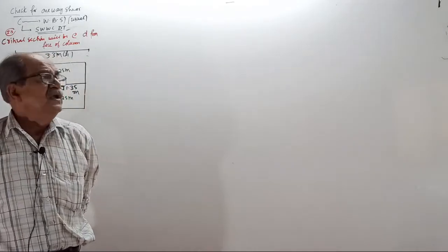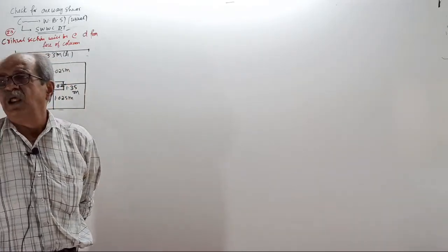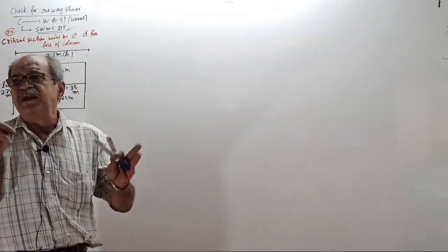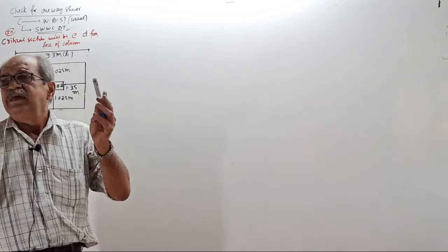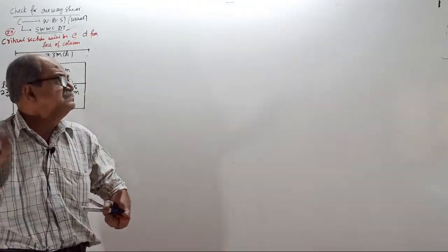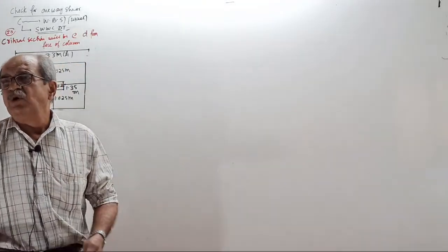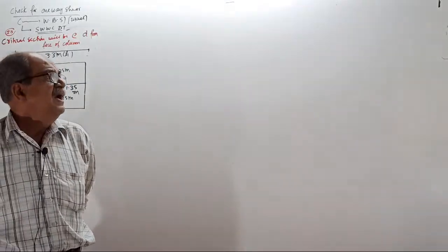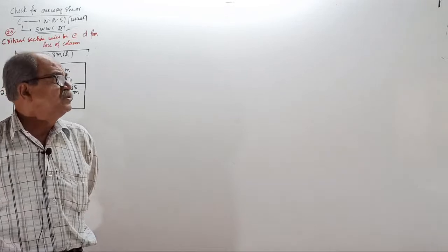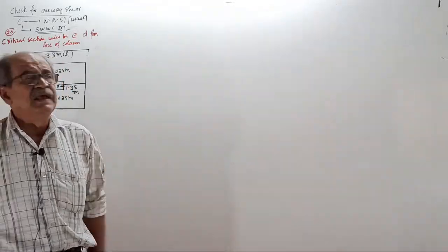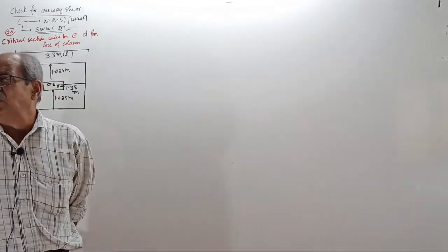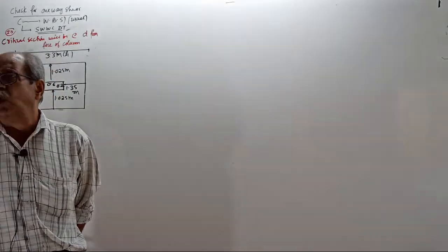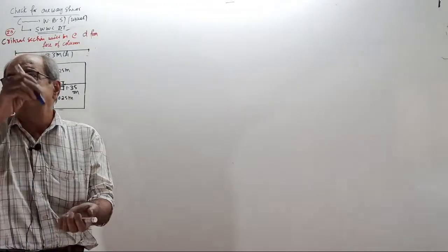I will make some concept clear now because later, when we enter the real practical case of footing design, from the column you get not only axial load; in every practical design M1 and M2 will come. There we have to worry about pressure variation and how to fix the footing dimension so that maximum pressure does not exceed SBC, and also there is no lifting. If it is purely axial load, no lifting.